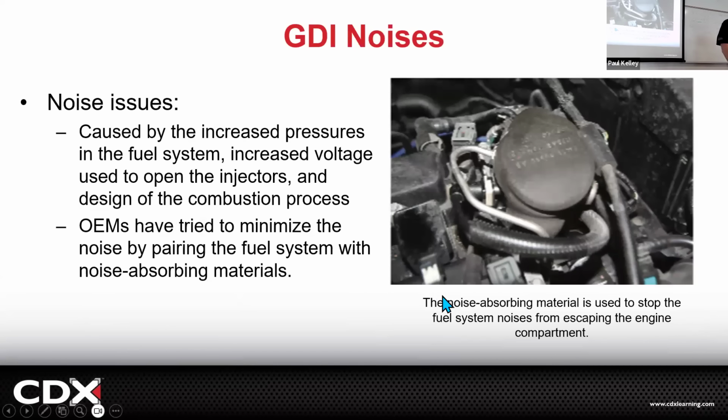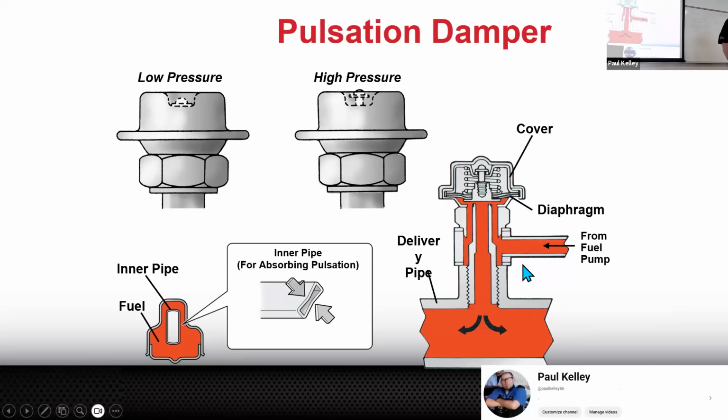Remember that pump, how it's getting punched in the face? Do you think you can hear that? I'd say so. So we're going to put like a little foam on top of it, a little engine cover, maybe a little dampener, maybe some sort of little dampening spring. We're trying so hard to quiet that down. I remember the very first GDI car that rolled in for me was a Pontiac Solstice. It rolled in and the customer said, "Hey, this got lifter tick." And I was like, "Oh man, it sounds horrible."